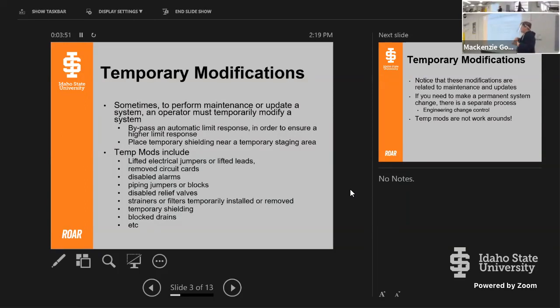So therefore, there's a temperature that's its melting point. And so that temperature is here. Our safety limit is going to be here. The temperature where we scram is going to be here. The temperature where you can no longer continue to go up in power and remove rods is here. And the temperature where you get your first alert is down here, right?